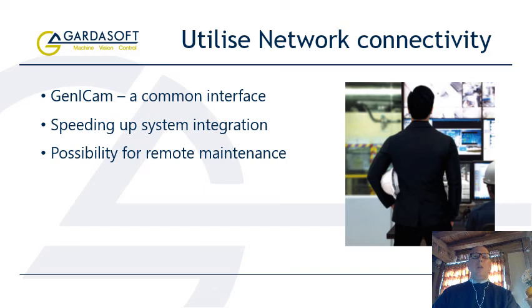Ethernet communications also offer the possibility of remote troubleshooting a vision system, which is invaluable when you could be many hundreds of miles away from your client. Adjustments might be made to increase the current into a light whose intensity has reduced due to aging. Ethernet connectivity also enhances flexibility by allowing the configuration of a lighting controller to be changed, for instance, to suit different batches of product.